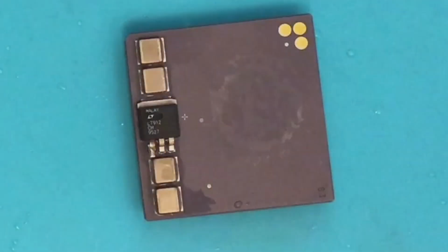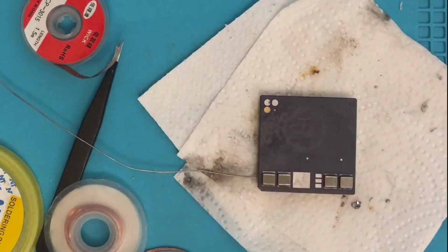However, in the end there are more problems with this approach here, so it's not ideal either way for high overclocking. You see, the problem is that this voltage regulator dumps heat on the ceramic of the CPU, and that is actually a lot of heat. So here maybe 1/3 to 1/4 of the generated heat is from the voltage regulator. So in the end, if we take everything into account, it is better to remove this and have something external to generate our V-core here. And yeah, this is what I did in the end.